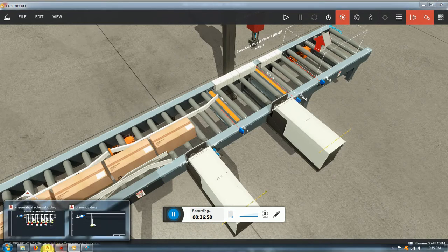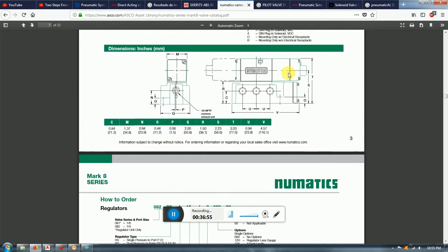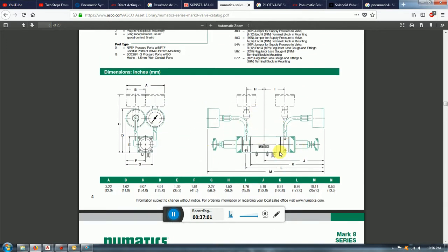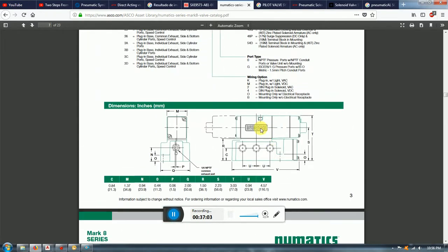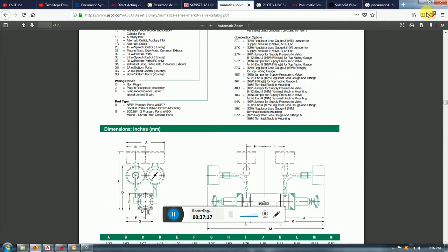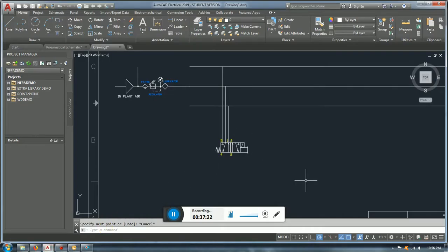So what we're gonna do is, in this case, some of them, apart from the solenoid valve and the manifold, could have that thing, okay? That thing you install on top of some of the valves. That is a regulator itself. You can see here, you have the gauge. You can see here, that is the wheel that you're going to use to regulate the air. So you can actually regulate the air that is going to be coming. That is awesome. And you're going to personalize it for the specific cylinder. So some of those are going to be like that. Some of the other ones are going to be different.